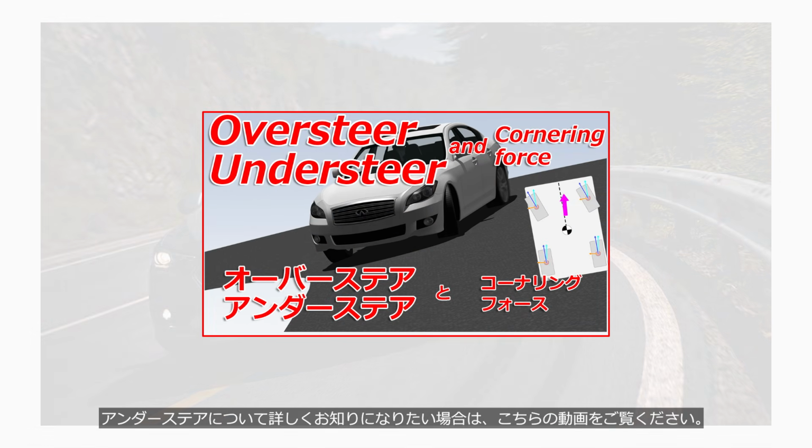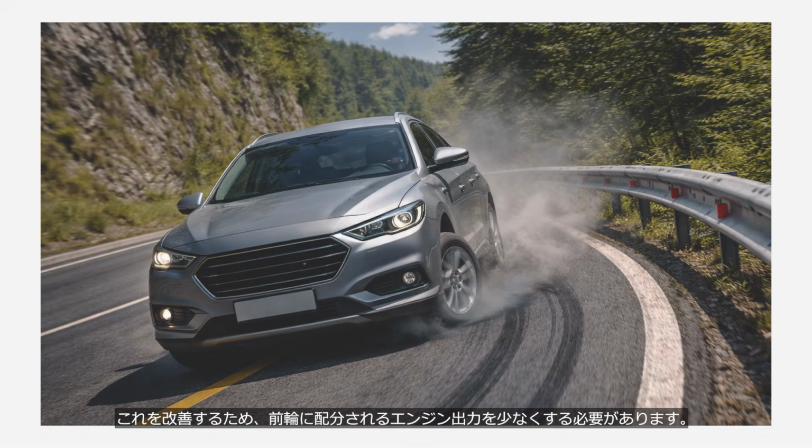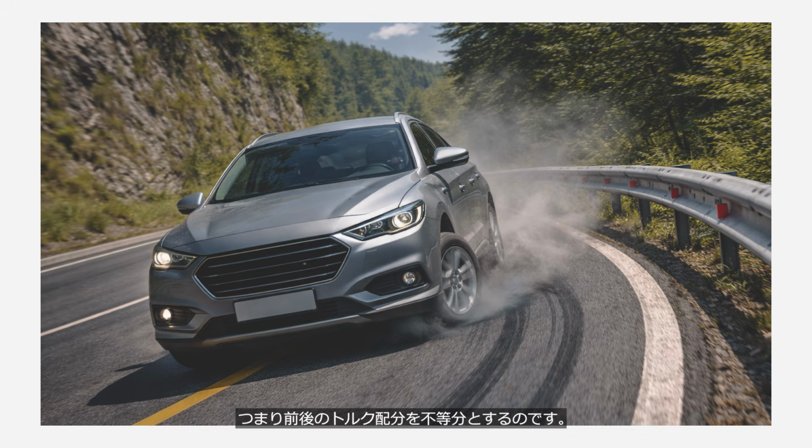If you'd like to learn more about understeer, please check out this video. You'll find the link in the description. To address this issue, it is necessary to reduce the amount of engine torque sent to the front wheels. In other words, an uneven front-to-rear torque distribution is required.